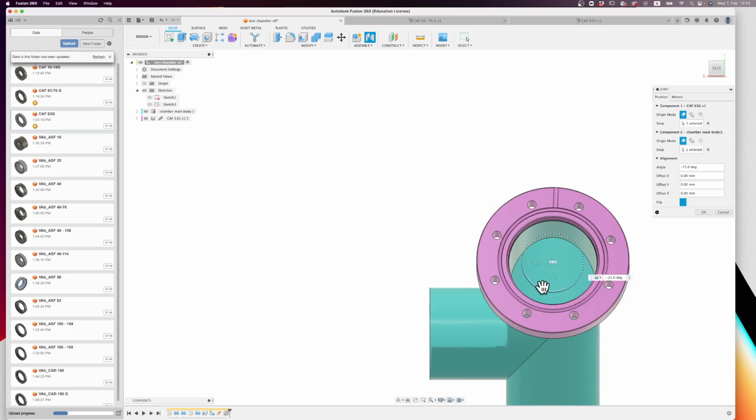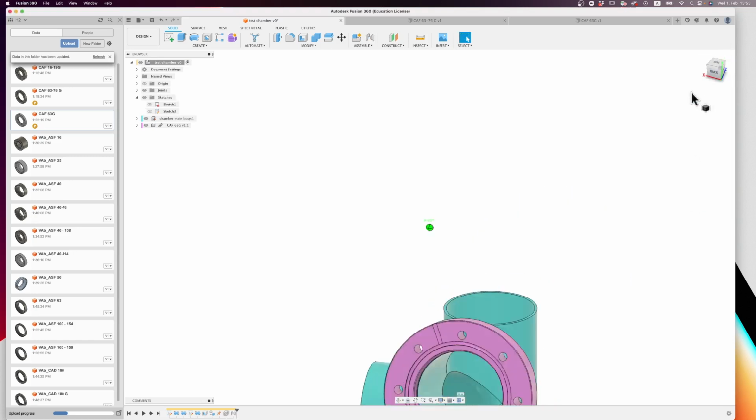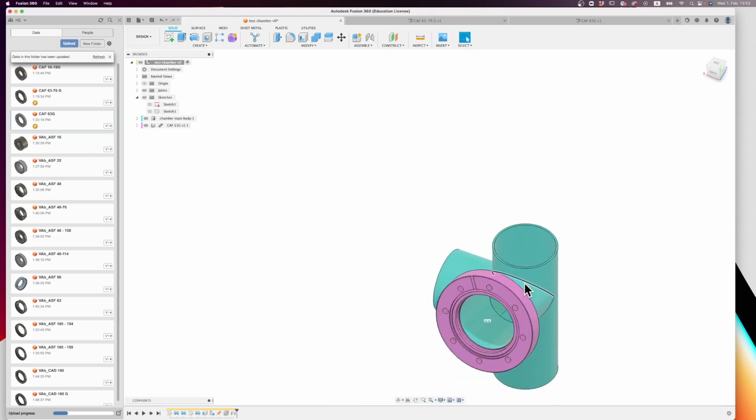In this case, we've got two main orientations. You'd have to move it by 22.5 degrees, either this way or this way, or if you need it, anywhere in between. But this needs to be specified. It's very important, because your manufacturer is going to look at that and weld the flange to it exactly the way that you specified.